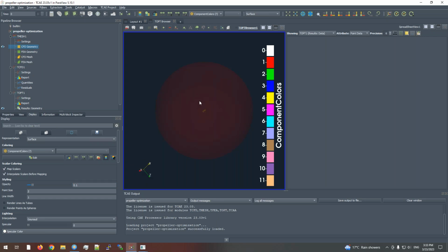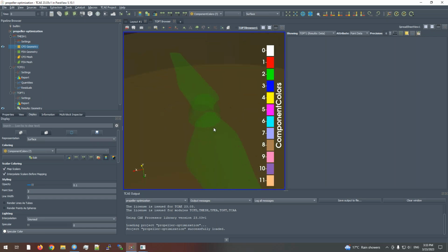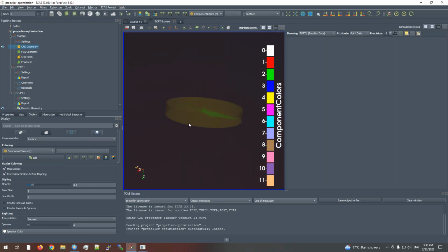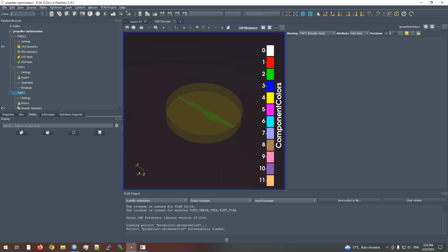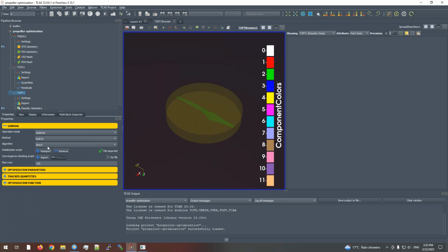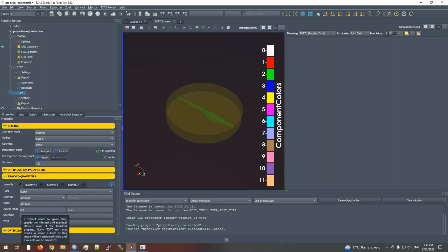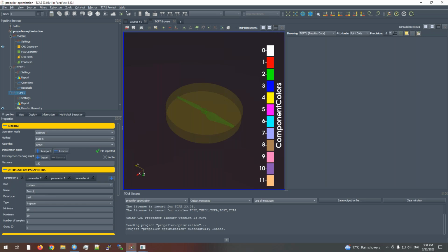So this is the big domain, which in its center has the propeller placed as the rotating region, and the TOpt is basically a standard optimization where the direct method or algorithm is run up to, say, 150 runs maximum. As optimization parameters, 4 of them are picked: 2 twists, some general beta, which is the overall angle of attack, and the thickness of the blade at some position.